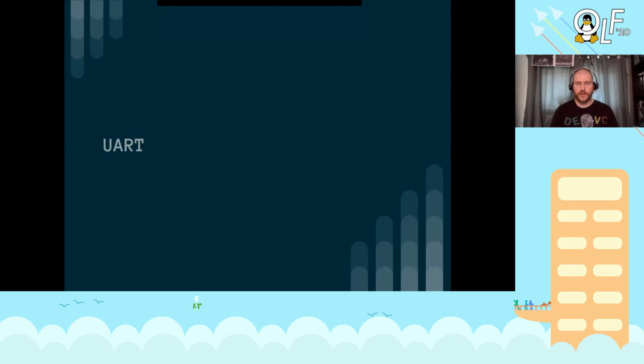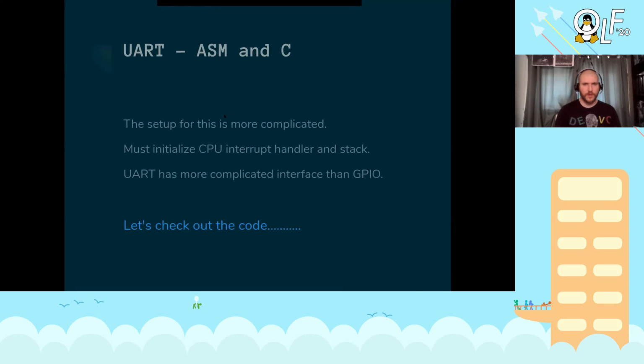So now we're going to make a serial port or a serial connection, and we're going to write a driver for it. In Linux, you kind of have an interface that you would implement maybe a character or block level driver for a device. Here, we're going to talk just directly to the hardware. So there's no abstraction for writing a driver. It's not a module that we can load or unload at runtime. It's just we are talking to the hardware register just like we did with the LED.